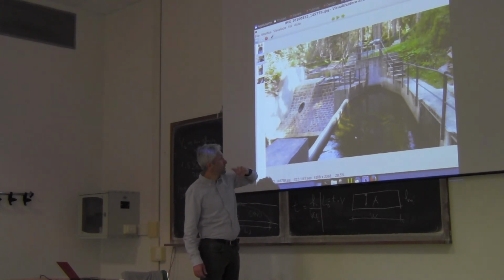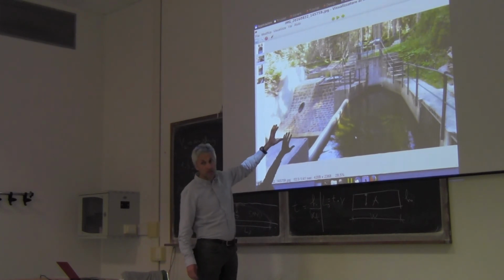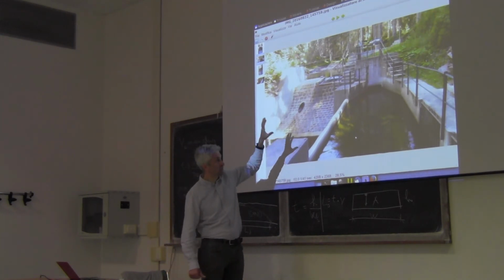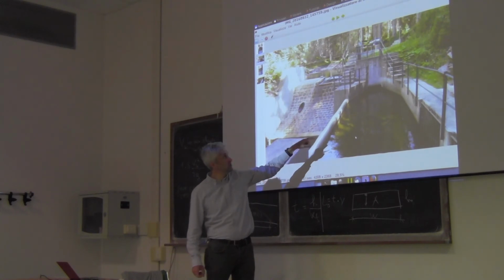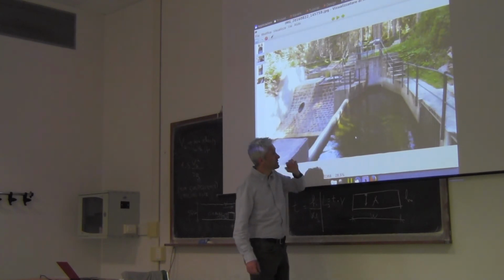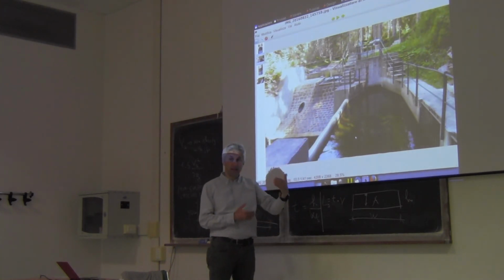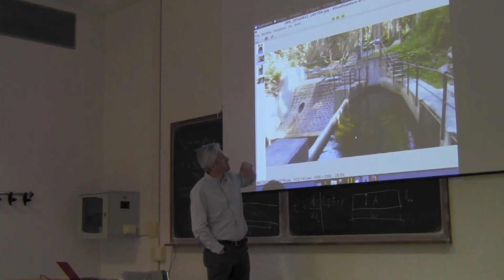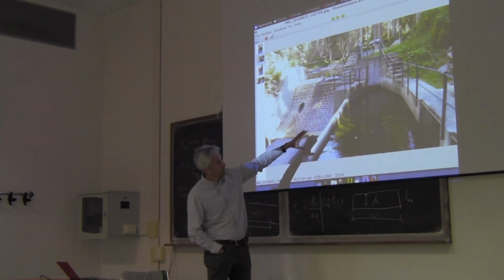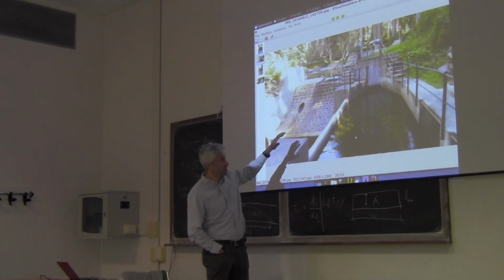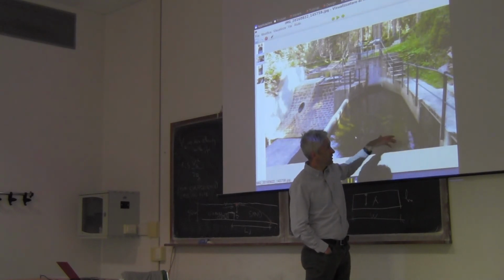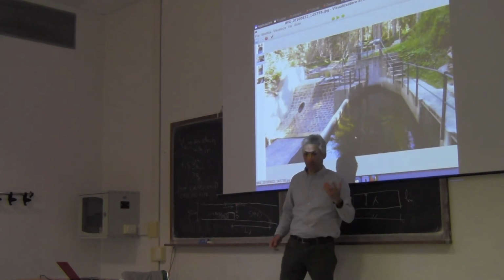There is no environmental flow weir here because this is an old structure, and the environmental flow is today released after the gravel trap and sand trap, which is here. You have the water that from the grid is transferred to the sand trap here, and it's a unique pool, sand and gravel trap. Keep in mind that in this river there is not much sand. The typical size of sediments is quite large. And then from the trap you have a release of the environmental flow, and through a grid that is located here, you have water that is conveyed downstream with a pipe.